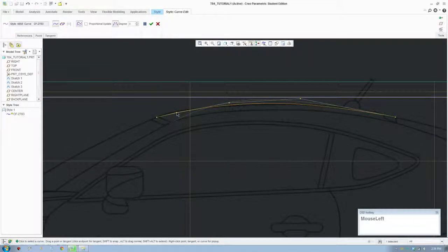So to delete the points, right click delete, but if you have a degree 3 curve, you can't delete. It needs to be more than 4 points. So when you draw your curves, make sure it's basic and simple. Use the minimal number of points as you can.